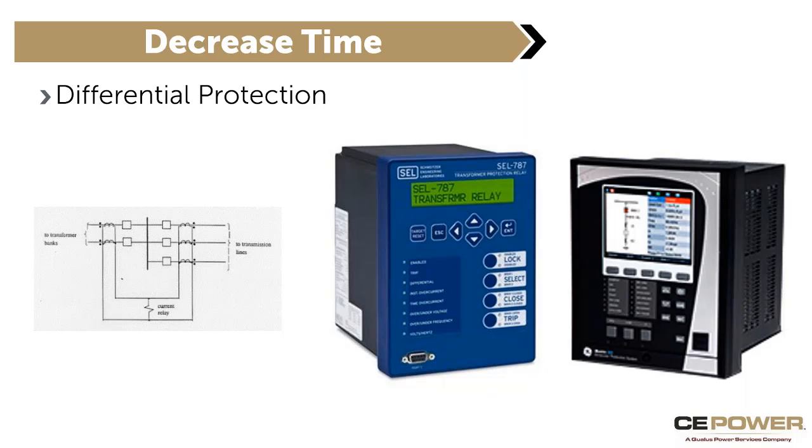Differential protection, again, it's been around forever. Current in, current out. These days with some of the Multilin products, you can absolutely open that circuit very, very fast. So it's utilized a lot for not only bus, but for transformer protection. So in the event of some kind of failure, phase to phase, phase to ground, you're going to be able to open up that differential a lot faster and not only hopefully save lives, but save the equipment as well.